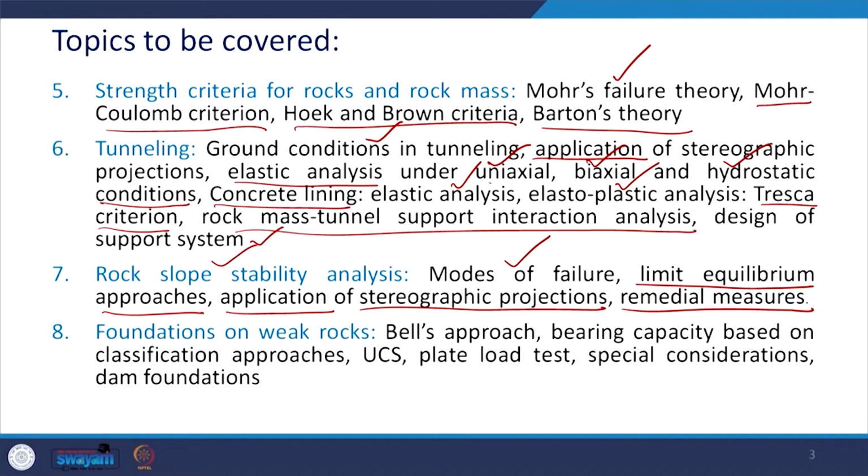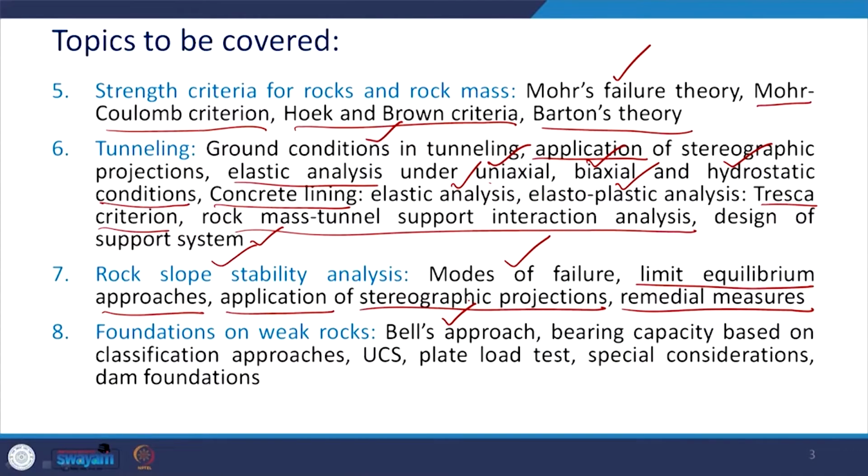And finally, we will discuss the foundations on weak rocks. You all know that in case of soil, you have Terzaghi's bearing capacity theory, but that does not work here in case of the rocks. So, we will learn about Bell's approach. Then the bearing capacity based on various classification approaches which we have seen, RMR, Q, etc., all those systems, based on UCS, based on the plate load test results, and some special considerations and some aspects related to dam foundations that we will be discussing.